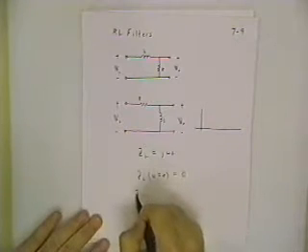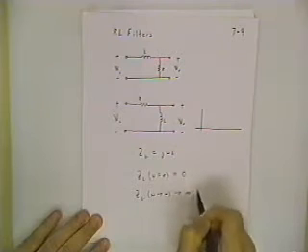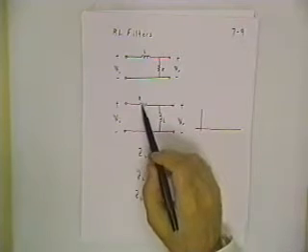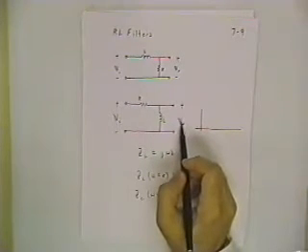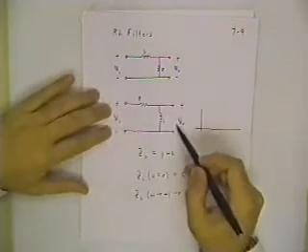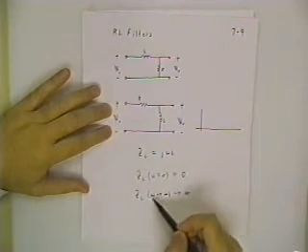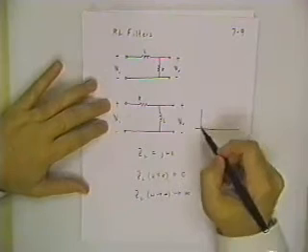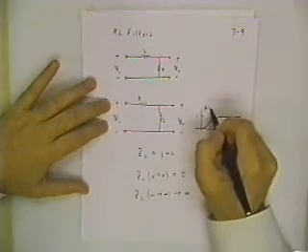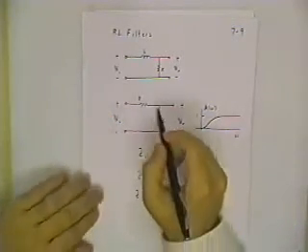High frequency, Z sub L when omega goes infinite actually goes infinite. And so when I'm at high frequency, this impedance is so much bigger than the resistor's impedance that the voltage divider tells me the output is going to be virtually the same as the input. So here we have for this circuit, looking at the inductor's impedance, low frequency gives us low output, high frequency gives us output equal to input, and so there's what my A of omega would look like. This is a high pass, RL.